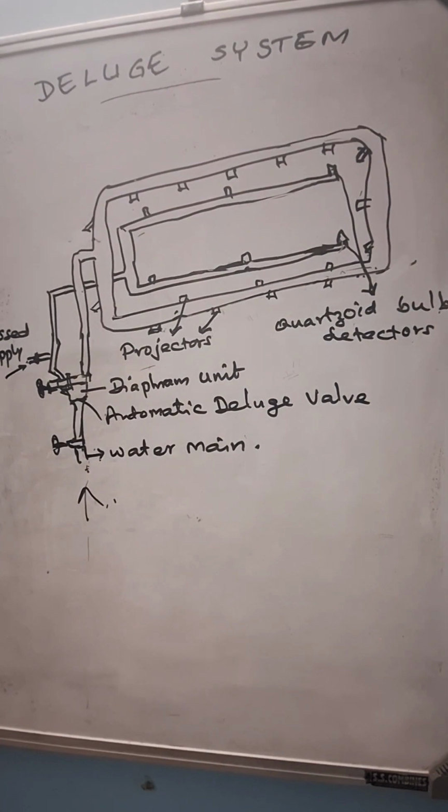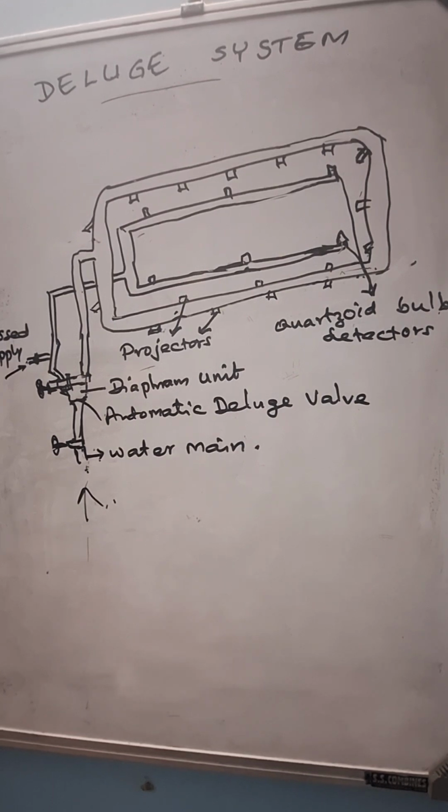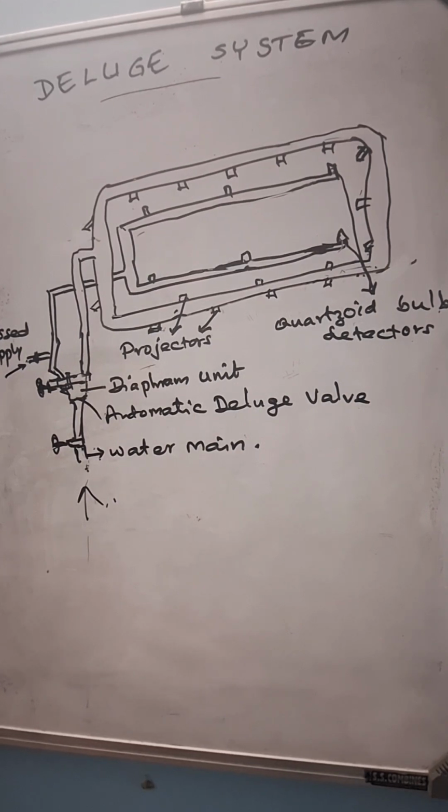In the medium velocity system, when a fire occurs, the system applies water in finely divided droplets traveling at medium velocity. It is used as a protective rather than extinguishing system, and it has the following effects: producing air turbulence in the vicinity of gas leakage, thus diluting the gas and thereby reducing the possibility of combustion or explosion; controlling the burning of flammable liquids by cooling their surface and the area above it, and by diluting the air and vapor feeding the fire; and cooling the external surface of exposed vessels and supporting structures, thus inhibiting fire spread, pressure build up or structural failure.